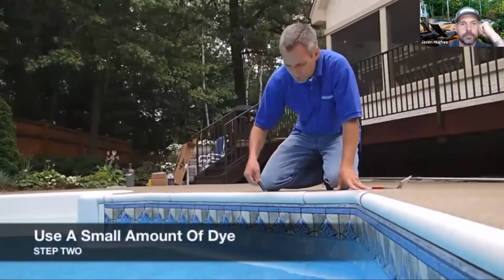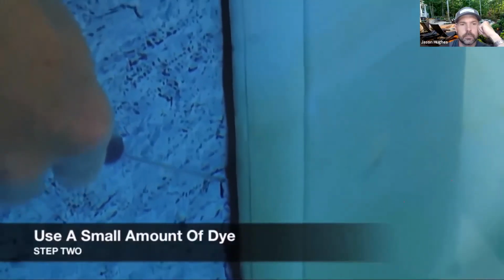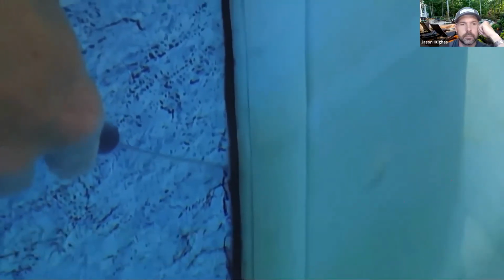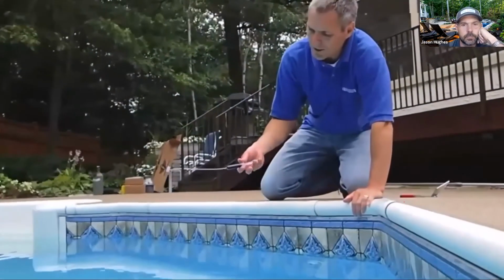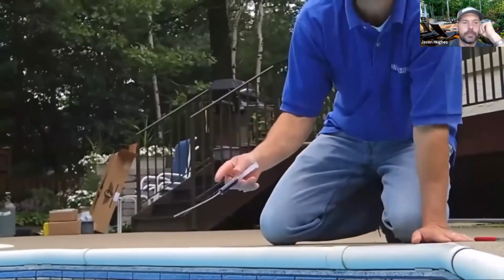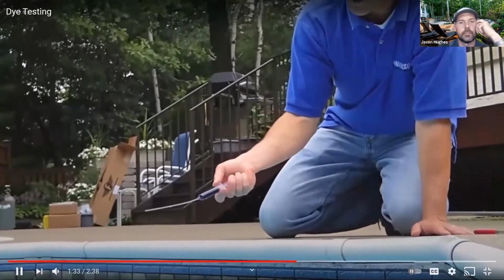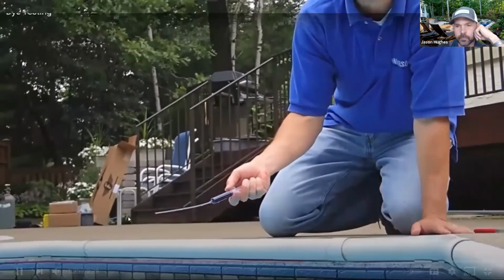Now we're going to put a small amount of dye right close to those suspected leak areas. I find that the easiest way to administer a small amount of dye is to hold the dye tester, not like we would a normal syringe with our thumb on top, but to use my thumb and my first finger to hold the barrel, and then the base of my palm to push the barrel in.